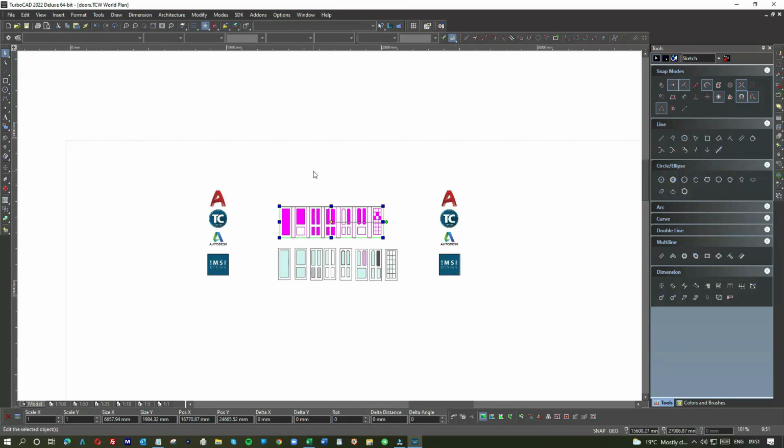For example, if I'm doing layouts on a house, then when I open the template, it'll have doors going left and right. It'll have bathroom fittings, the standard tub, sink, loo. So in other words, you create a template and have all the CAD block fittings that you would normally use in an average drawing. So it saves you going back out and in and out.